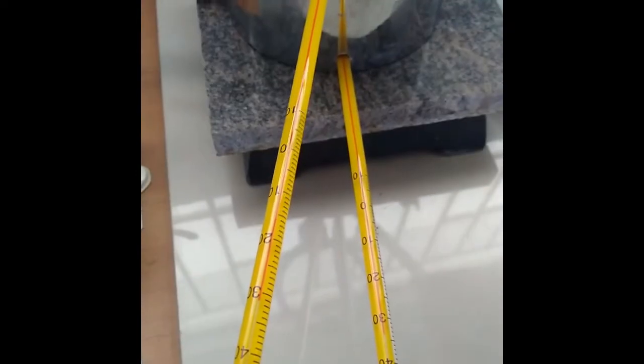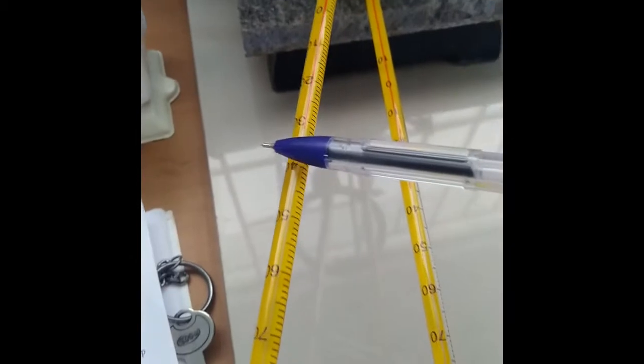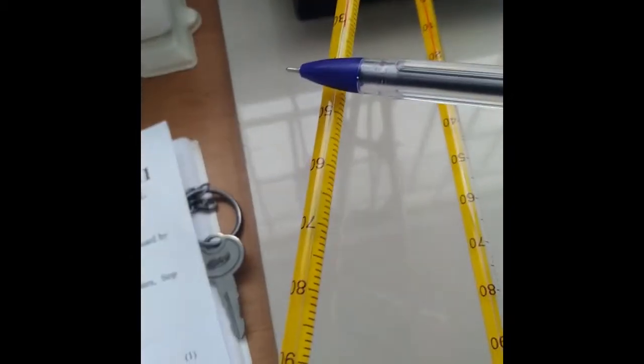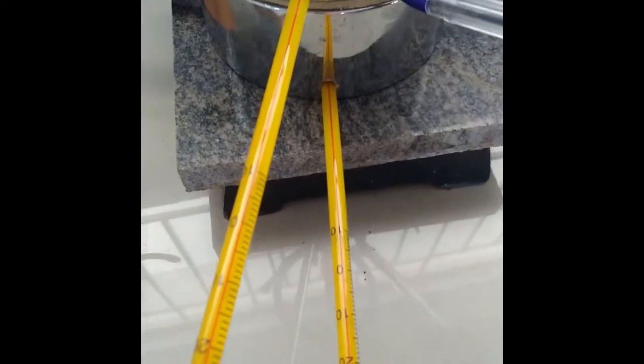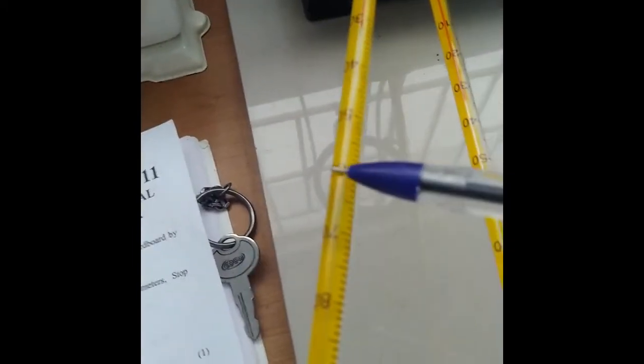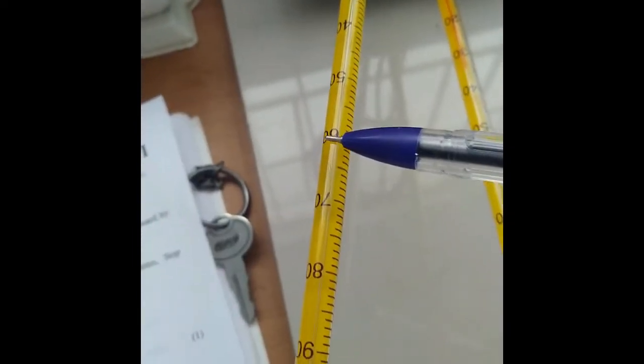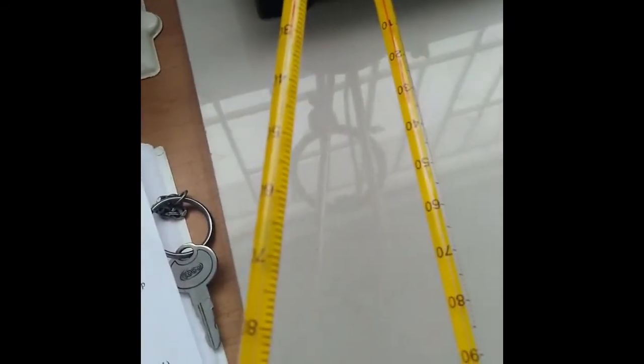So initially the temperature on the thermometer inserted into the Lee's disc will rise. It will never reach 97 degrees Celsius or 100 degrees Celsius, but depending upon the thermal conductivity of the bad conductor as well as its thickness, it will reach a steady state value that is much less than 97 degrees Celsius. Say for example, let us take it to be 72 degrees Celsius in our case, right?